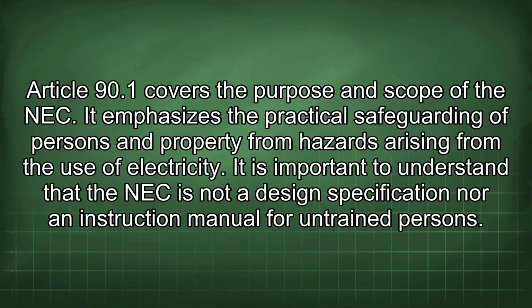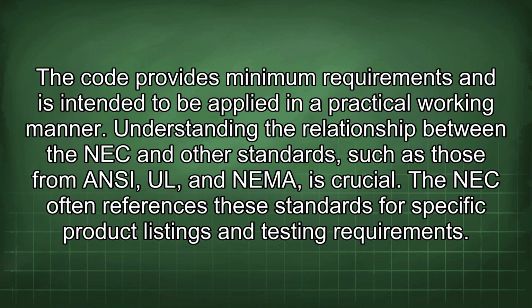Article 90.1 covers the purpose and scope of the NEC. It emphasizes the practical safeguarding of persons and property from hazards arising from the use of electricity. It is important to understand that the NEC is not a design specification nor an instruction manual for untrained persons. The code provides minimum requirements and is intended to be applied in a practical working manner.